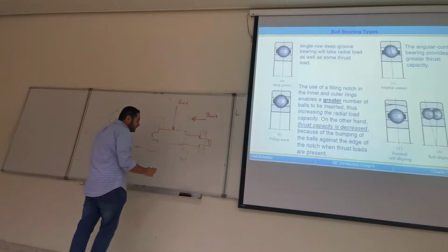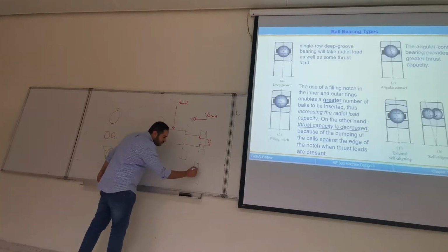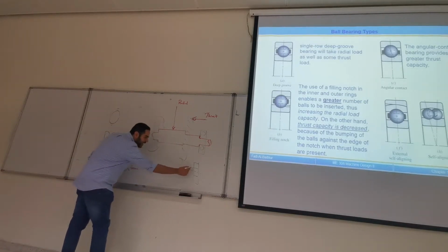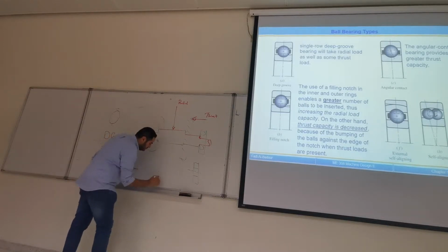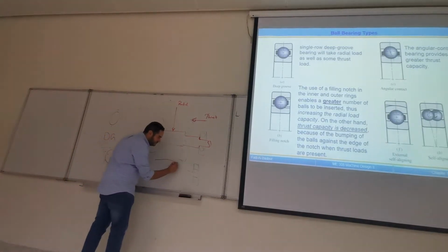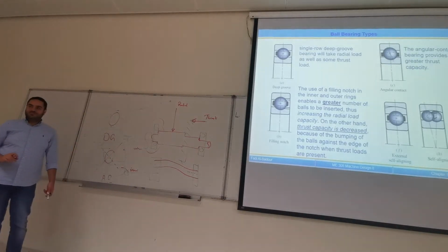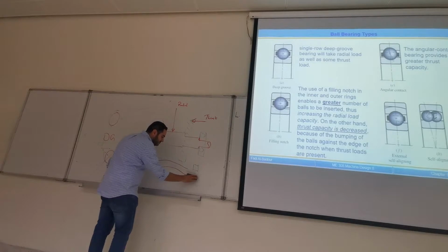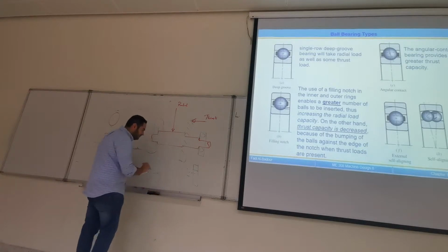So let's look at it from the top view. I have a bearing housing here. This is the center of the hole for the bearing. And it's supposed to be aligned with the bearing housing here, but there's a shift. This is the center. Now when I mount, the shaft cannot go like this. The shaft is not flexible to bend this way. Okay? The shaft will go like this. Here will not be straight. Here will not be straight. The shaft will go something like this.